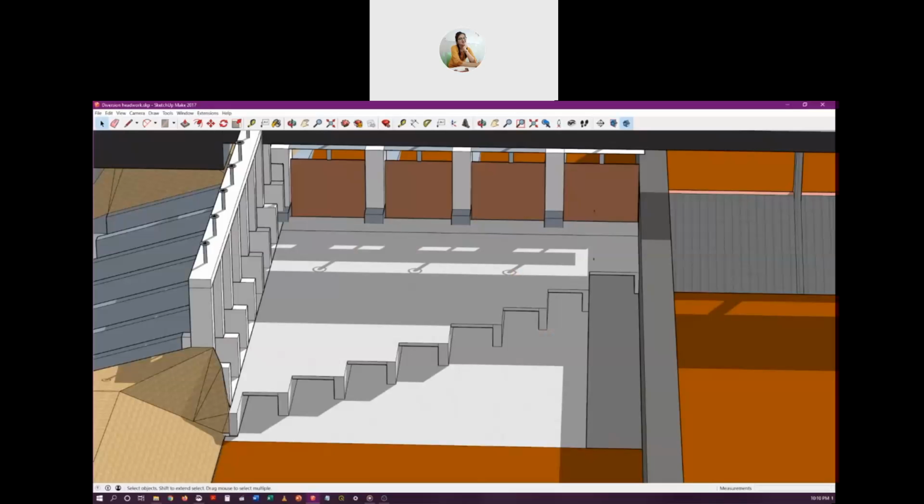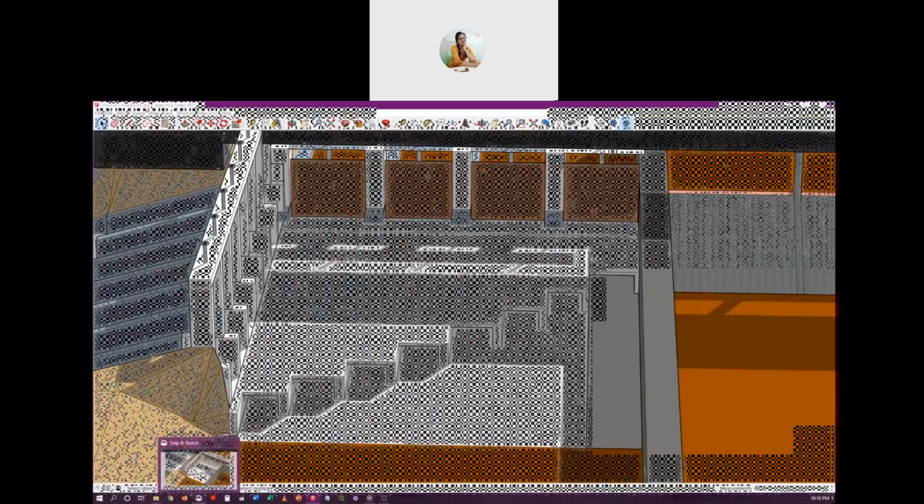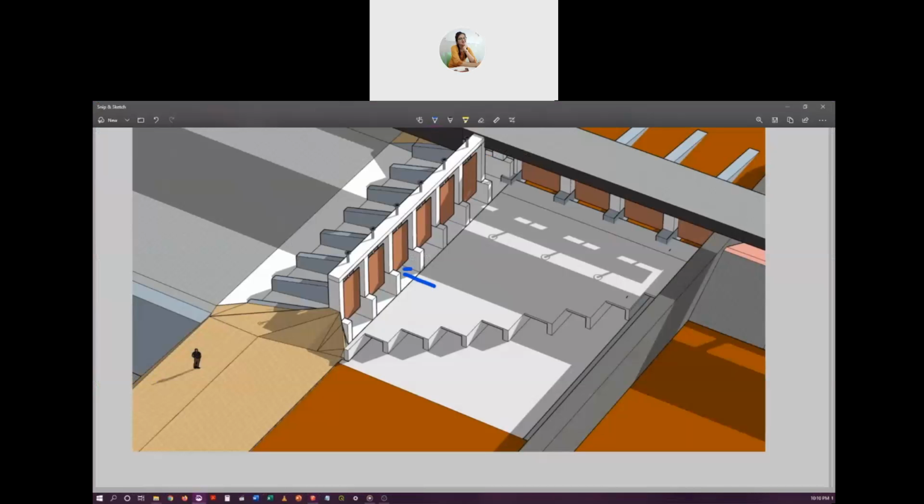The reason behind that is when water goes into these gateways, they have a velocity component like this. And if we had made all these tunnels of the same length, then because the velocity is happening this way, water will not enter these tunnels and will flow perpendicularly.